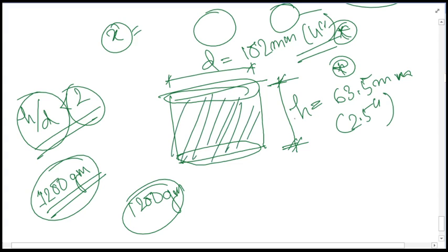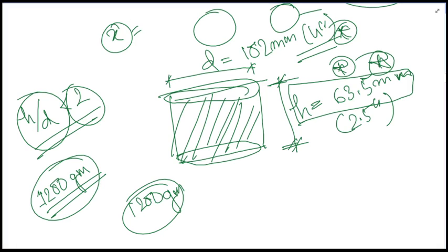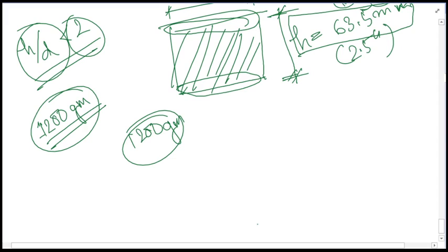So if it is not actually 63.5 millimeter, then you will have to apply a correction factor, as all other things are calibrated based on this 63.5. There is a chart for this which we must apply. If we don't have height equal to 63.5, then we will have to apply the correction factors, and about these correction factors I will be discussing now. The correction I am talking about should be applied to the stability value which will be finally obtained on applying loads.